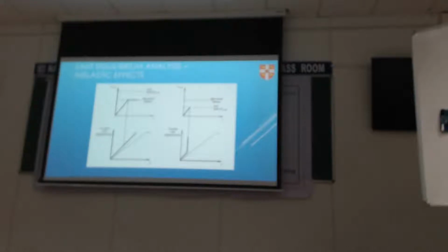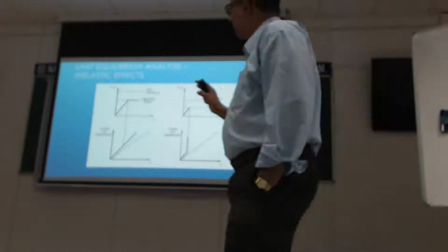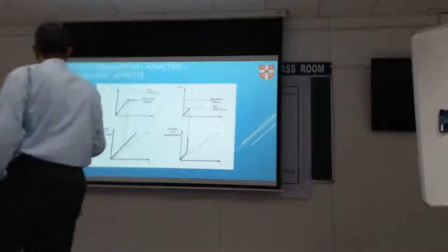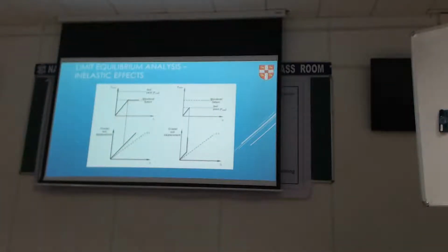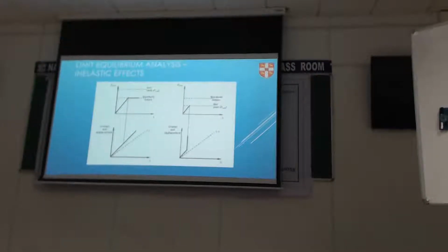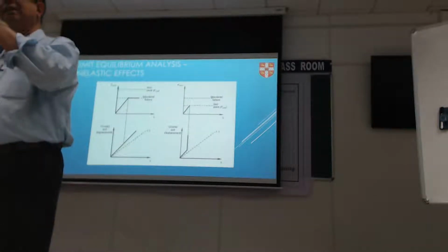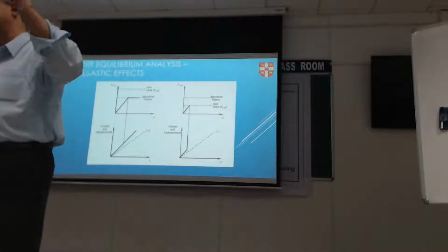Right. It's also possible to extend this concept a bit to include some inelastic effects. For example, I can adjust the difference in the movement of the crustal soil, or the non-liquefiable crust on the top, compared to the liquefiable soil. I said that it's possible that the crust can move more compared to the liquefiable soil because a water film can form and the block can slide down.